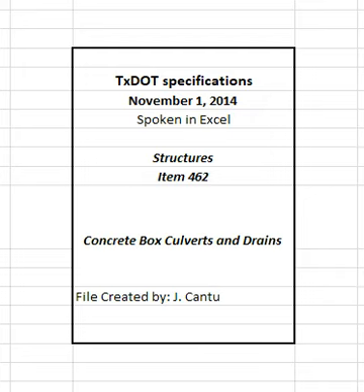3.3 Jointing. Use any of the jointing materials in accordance with the joint requirements specified in Item 464, Reinforced Concrete Pipe, unless otherwise shown on the plans. Box joints for rubber gasketed material may be substituted for tongue and groove joints, provided they meet the requirements of ASTM C1677 for design of the joints and permissible variations in dimensions.